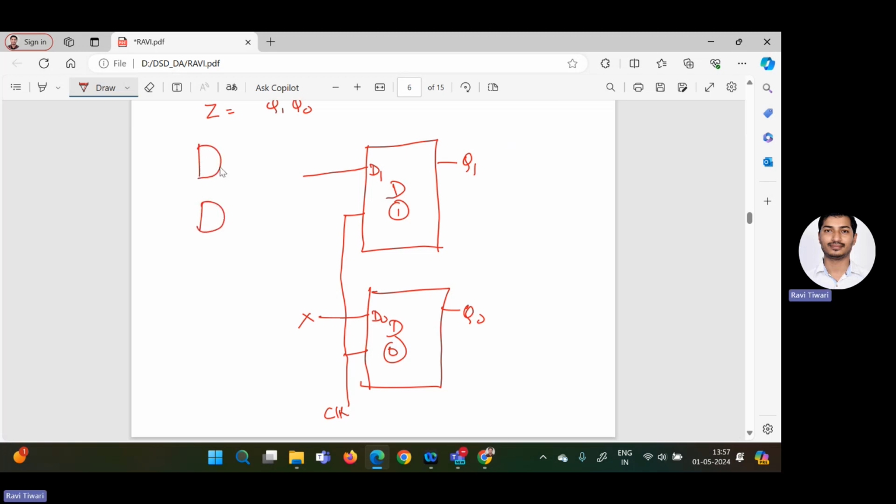So here I am giving it like this, and that is given to one OR gate. Here the three terminals are there, Q1, Q0 bar, and this is X. This is Q0, this is X bar. Similarly, Z will be represented by Q1 Q0, so that you can design by using the AND gate. So this is the final answer in the case of 101 Moore machine overlapping.